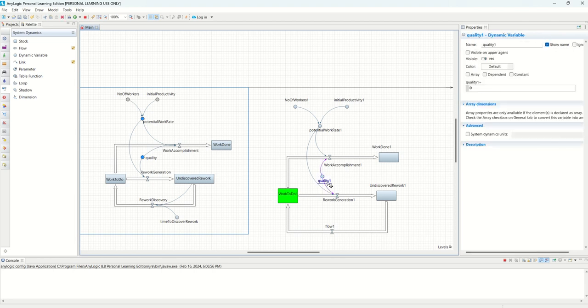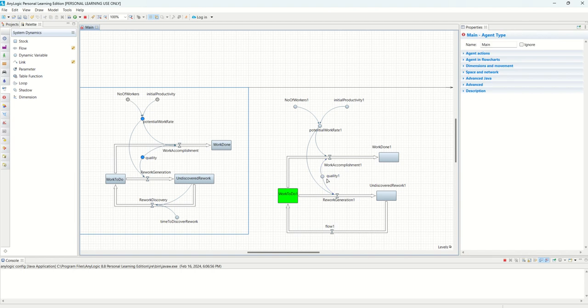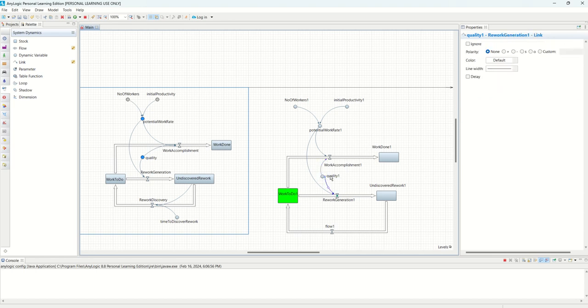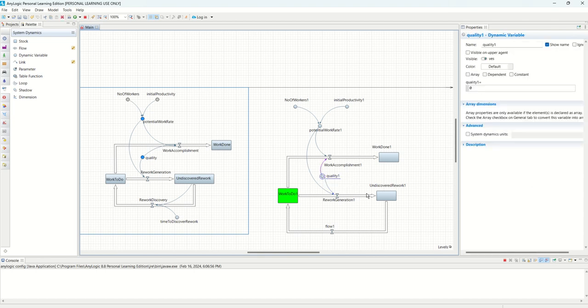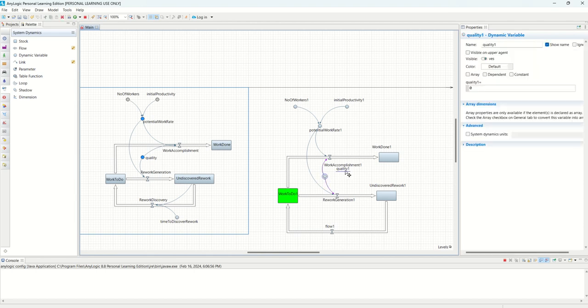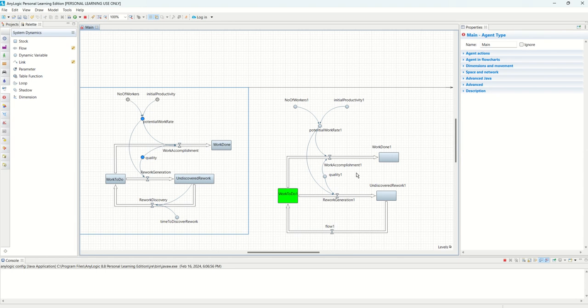and one more thing, make sure you connect the links. If you don't connect the links, it won't show here. So if you click this variable, these two links are active, right? But say if I don't connect it just a little bit here, now this variable is not connected with this link, right? So if I click it here, the only link it's showing me that's connected is this. So I have to drag this link here and put it here. So there's some tidying up that needs to go on, and if you want to click it, you can't see it here, so you have to click the variable that it's corresponding to and then drag it from there.